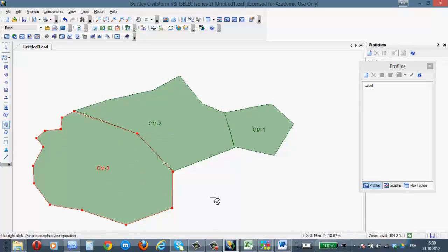Manholes are usually inserted in a stormwater model where it's necessary. For example, when there is curvature, meaning a change of direction, or when the distance is more than 30 meters, we have to add another manhole, especially if the sewer system will be cleaned manually. If it is cleaned by a machine, we can increase the length, I think.